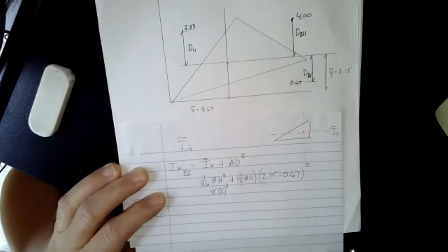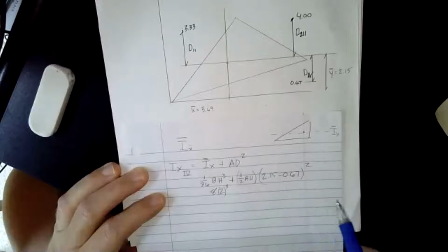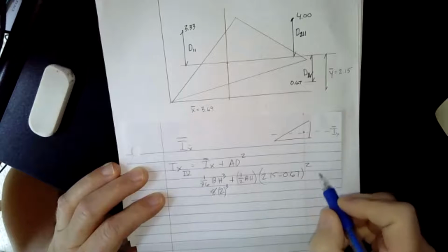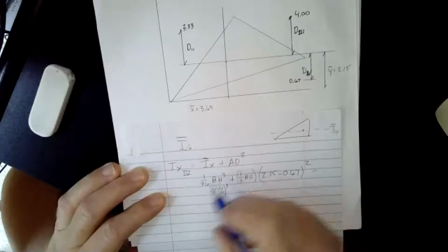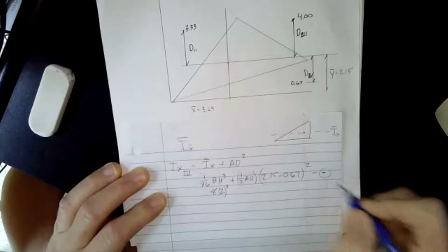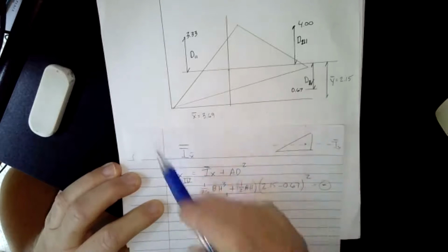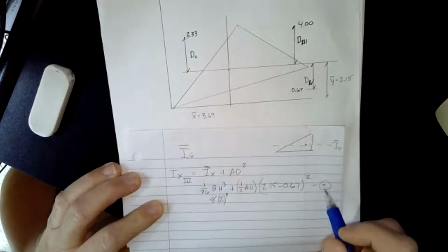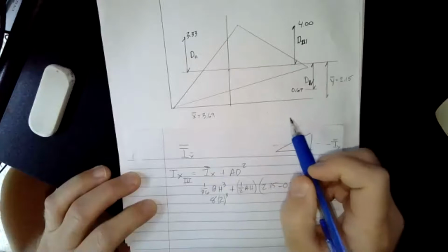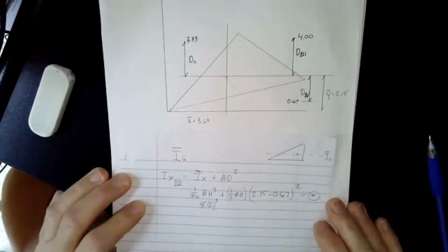And then that's squared. So it's not AD all squared, it's just D squared times A. So you go ahead and you get that number. And then of course, because that's an empty space, this final answer is a negative. That's the important thing when you're doing these parallel axis theorems: treat them as all positive, meaning that they exist. Don't put any negatives in here until the end, and then subtract off the entire value from the actual object. Okay, does that make sense? Any questions on that so far?